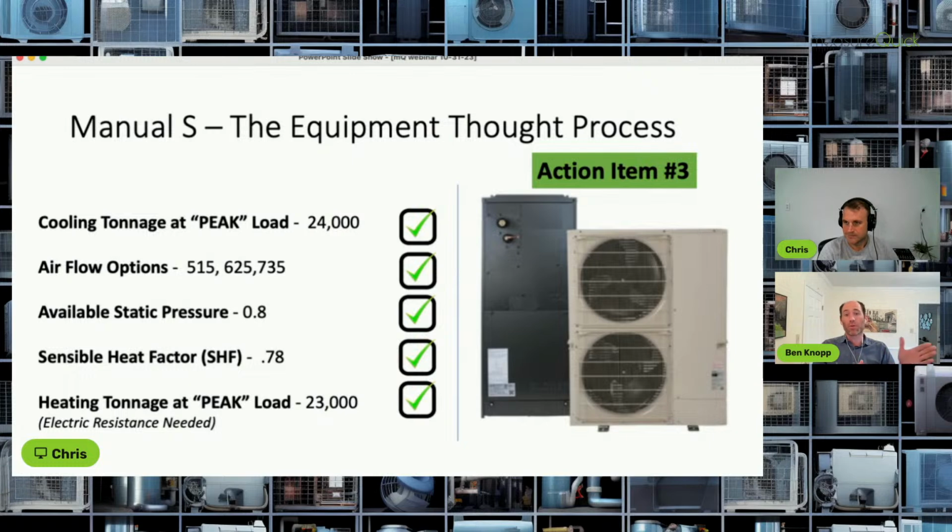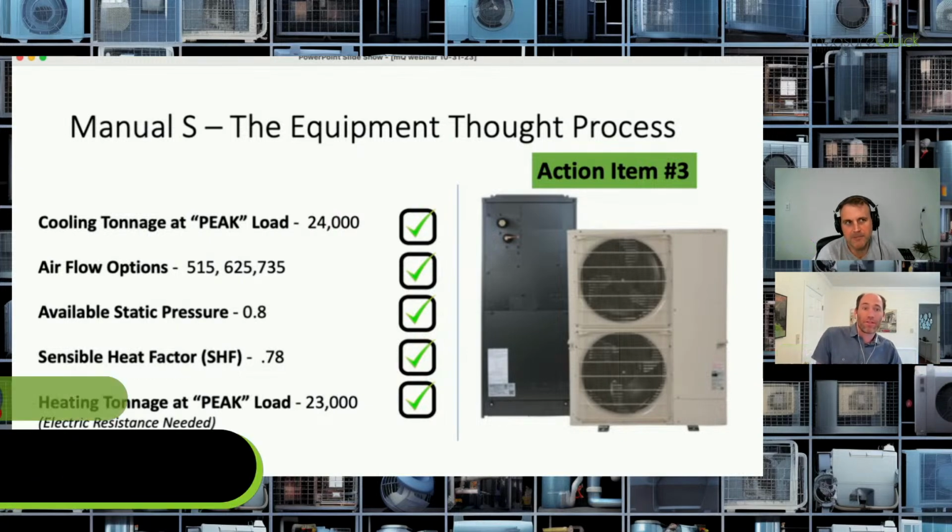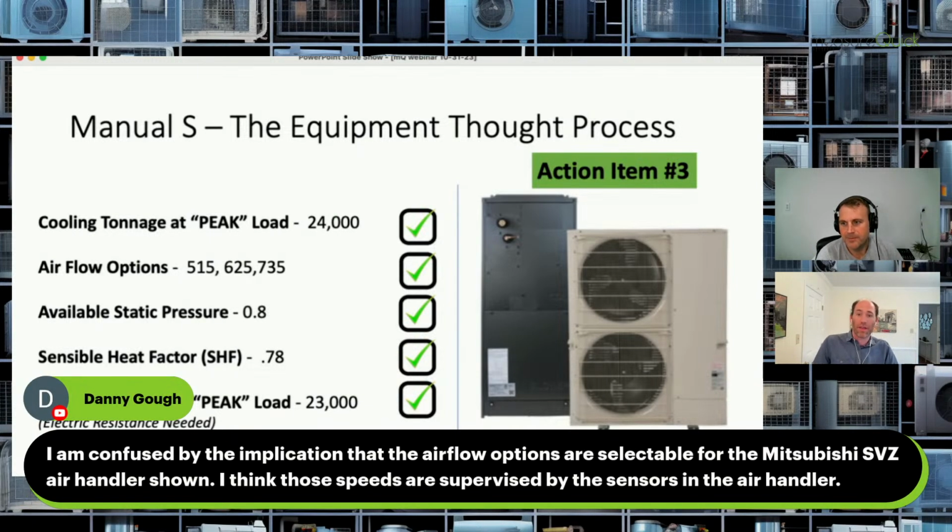When we went from 2.5 tons to 2 tons, there was a big jump in the turn down ratio. Essentially, if we had the 2.5 ton system, then it just would cycle off and on a lot. It wouldn't really get the full benefit of the variable speed compressor. Yeah.